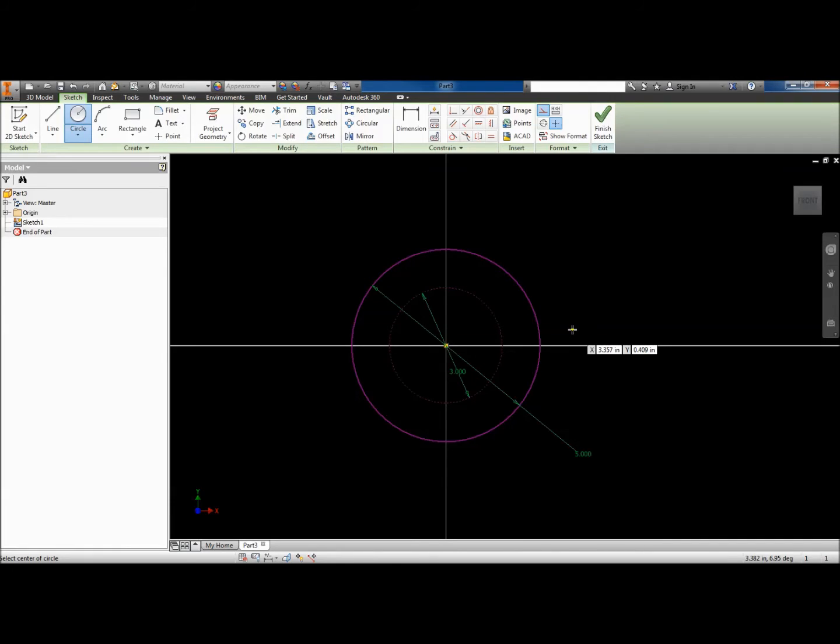Now, one of the things I'll need to do is create a construction line which puts my first hole right there. The next thing I can do is pick up the circle that will define the hole. These holes are 0.62 inches across in diameter. As I did that, the circle I have installed is in construction mode. That's easy to change simply by clicking this button off, and it will set that up.